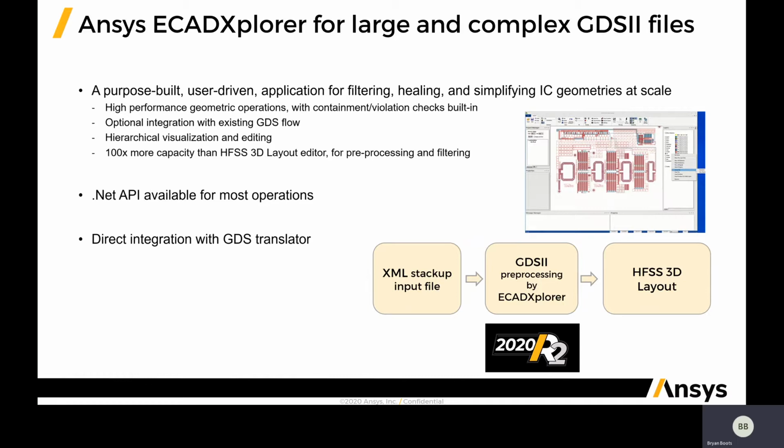So we've really focused on high performance geometry operations specific to on-chip structures. And when operating at that scale, containment and violation checking, having those checks built into the geometry operations is critical. So we do integrate those sort of design level checks with the geometry processing.